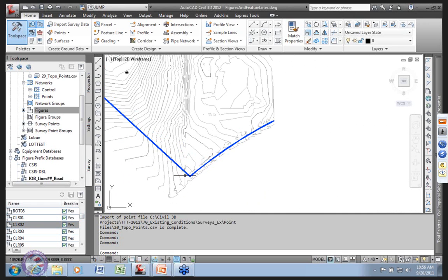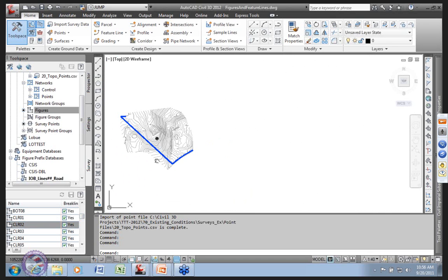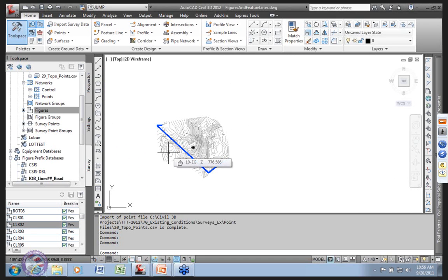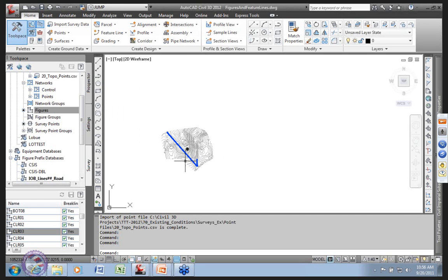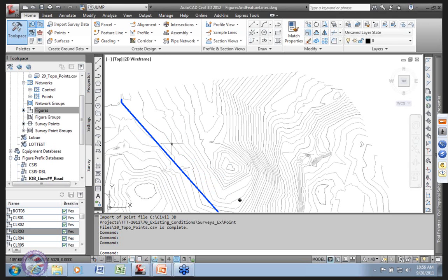And remember, we can go and see where the breaks are. So even if I have no command codes at all, I could still get a whole bunch of figure information out of a point file. It takes me a bit of time to chew it up, but it's still directly related to that point data, and recreatable, editable, malleable.